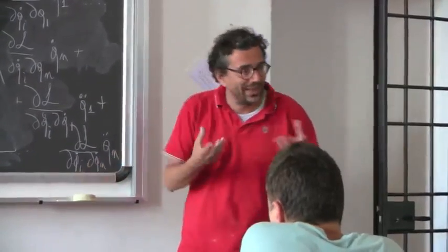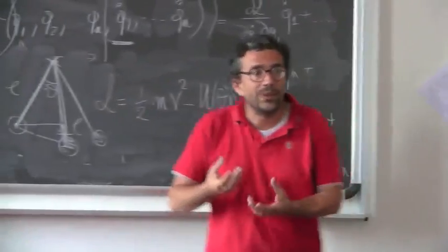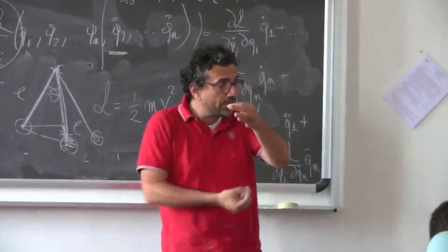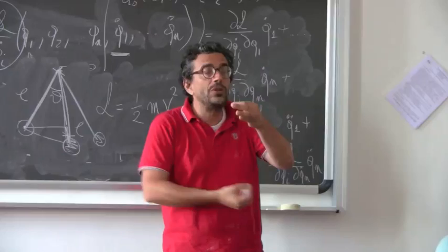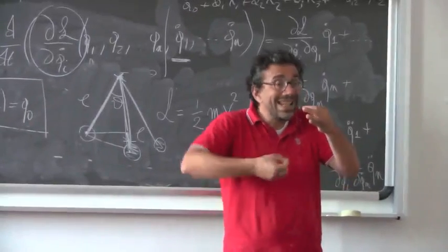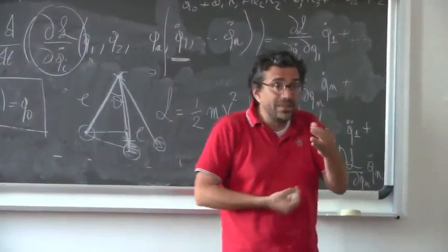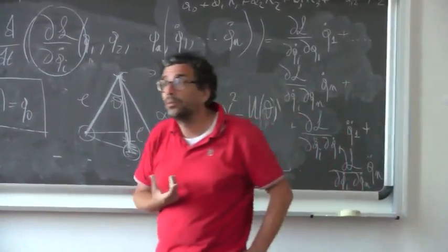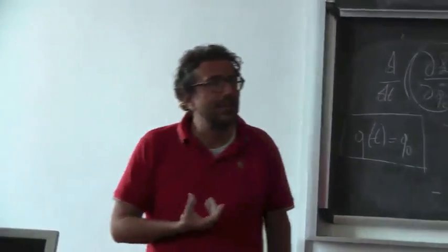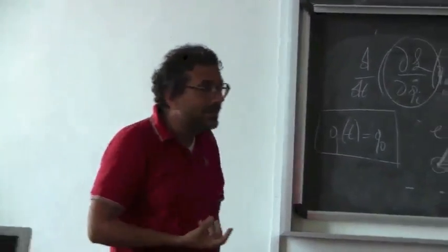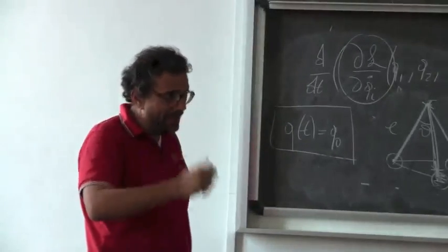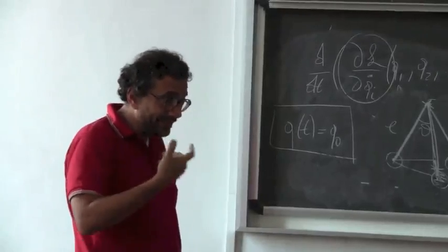What Galileo is doing is finding the equation of the small motion in the neighborhood of an equilibrium condition, linearizing the equation of motion. Why this linearization? Because linear equations can be solved sometimes by hand.